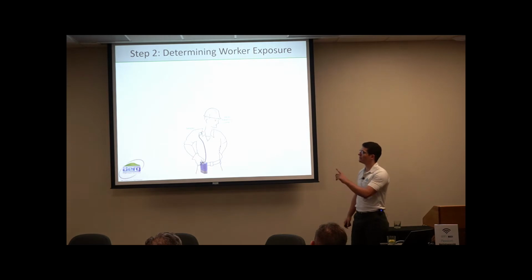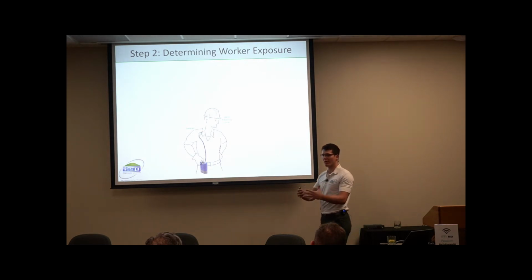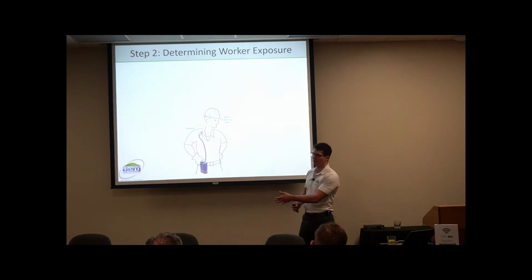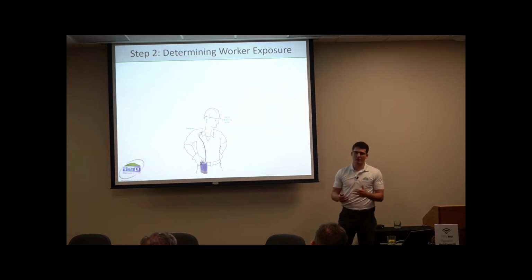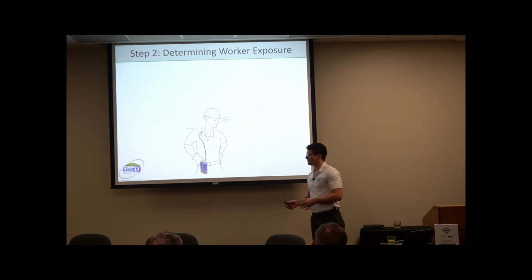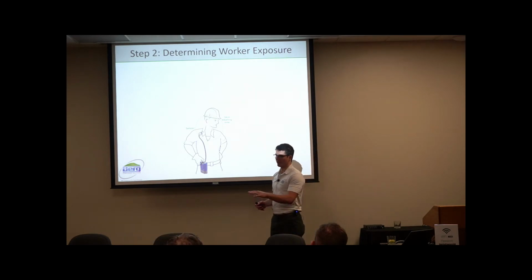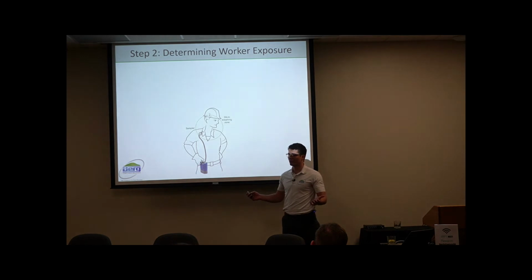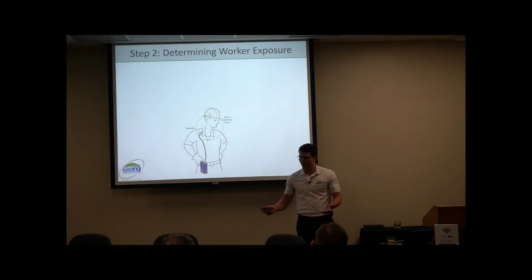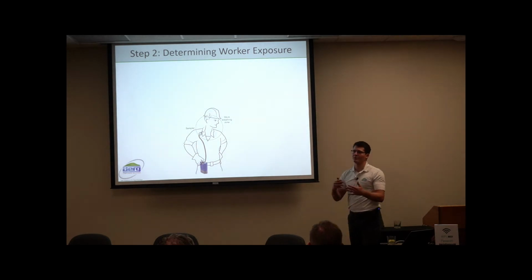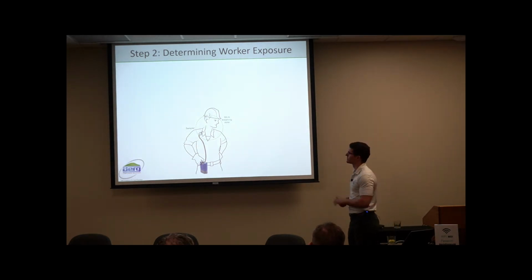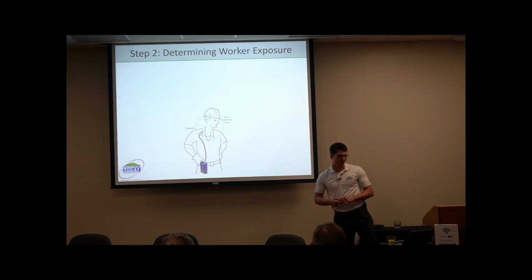What if you did all your controls, as many controls as you could possibly do and feasibly do before sampling, and do the best you can to do that, including respirators, obviously. And then you monitored. And since you had already put all your stuff in place, it was good. You had enough ventilation and you were below the limits, so now you don't have to monitor again, right? So it kind of saves you time and money in that case, right? And satisfies the intent of that standard. That's the reason why I put this second, all right?